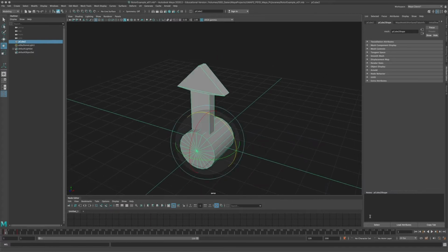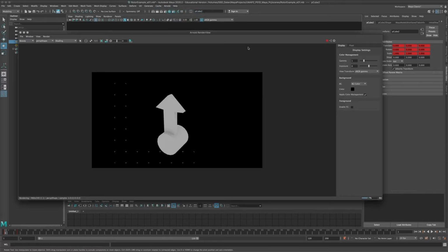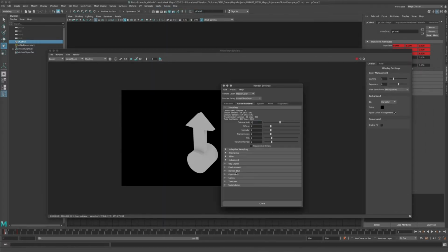So this is rotating now, and this is actually rotating pretty fast right now. So how much does it move actually? It moves a full 90 degrees per frame. So if we are going to render that and we want to turn on motion blur, we want to turn off deformation motion blur, because really we're just animating transforms, and if you have a large scene and the plane is not a ridiculously large scene, but there's some geometry there, so exporting the deformation information for every single time step within that frame, because you have to export more than the actual frame to the renderer for it to calculate your motion blur, this will take time.